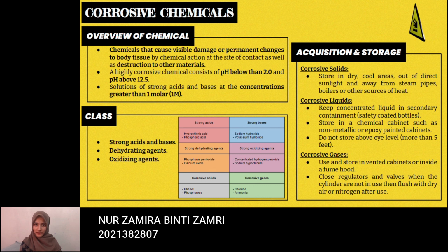Third, corrosive gases. They must be stored in a vented cabinet or inside a fume hood. Close regulators and valves when the cylinders are not in use. Flush with dry air or nitrogen after use.